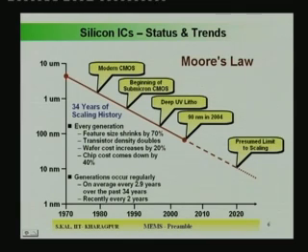You can see from here the modern CMOS in 1980, which is nearly 1 micron technology, and then at present in 2004 the transistor size has come down to 90 nanometer only. And here basically a roadmap is given by an international organization, which they call the semiconductor roadmap, and over the last 34 years the scaling history is such that every generation the feature size shrinks by 70%.